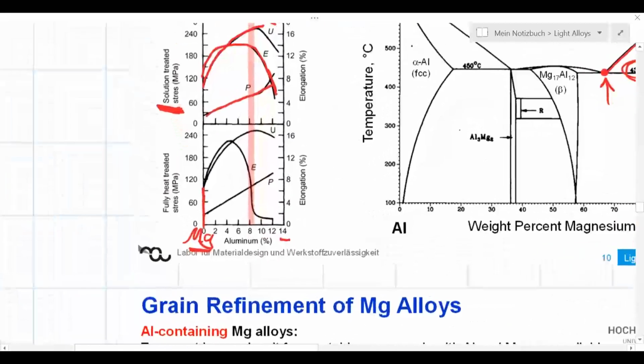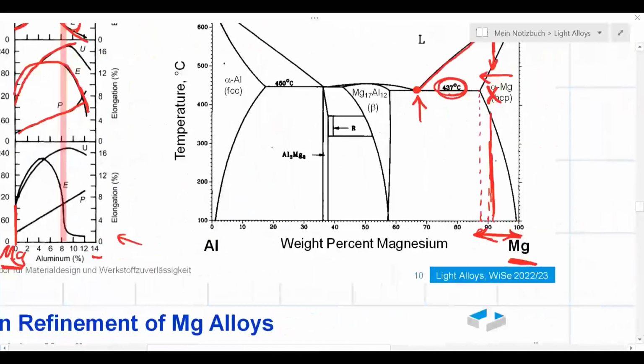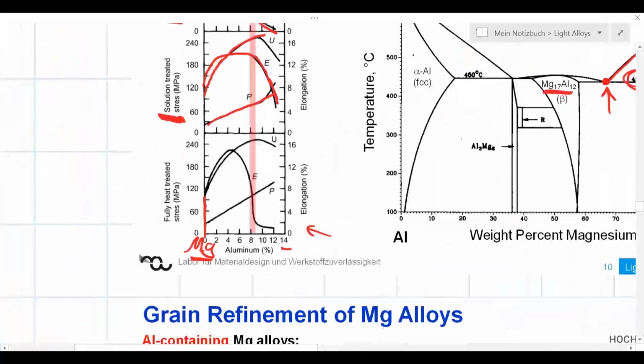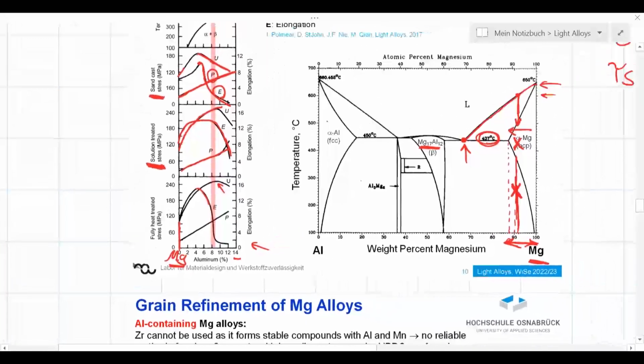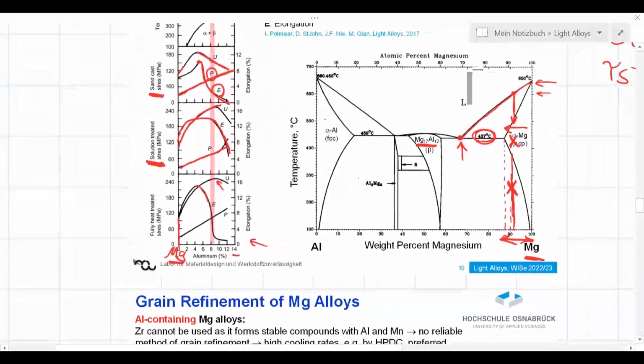Good. These are also some values. If you do further processing, further heat treatment, depending on what happens, if you are going to get, for example, some precipitates, if you do a heat treatment here, for instance, then we could start to get some precipitates or beta phase, and that could also influence mechanical properties. Elongation is going down, but in spite of that, we are getting a high UTS value. The detail about the processing is just saying fully heat treated, but the exact processing was not indicated. But at least with this processing, we could get a high UTS value. It's a high strength alloy.